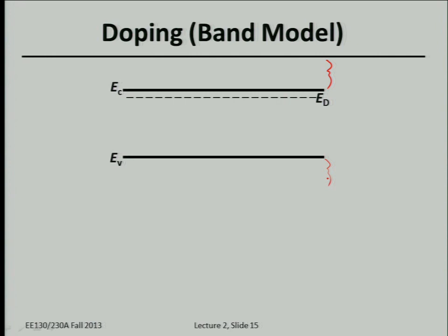That means the energy level of that donor electron state has to be close to the conduction band edge. So it's very easy for an electron, which is one of the 5 outer valence electrons of the donor, to escape and move around in the lattice. That means it's occupying the conduction band. Does that make sense? So we know that any donor electron energy level has to be close to the conduction band edge in order to allow the donor atom to ionize very easily.